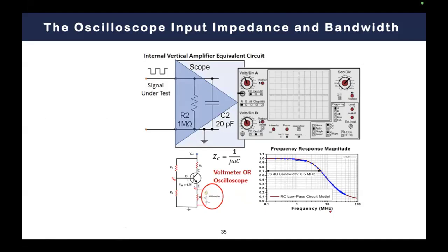If you are operating at relatively medium frequency in the megahertz, you can ignore the picofarad capacitance. But if you go to the gigahertz range, you have to consider the resistive loading, which is a relation between your resistance and the input impedance resistance. The input impedance resistance is in the mega ohm range. So if your resistance is in a comparable range, you have to consider it, otherwise you can ignore it.